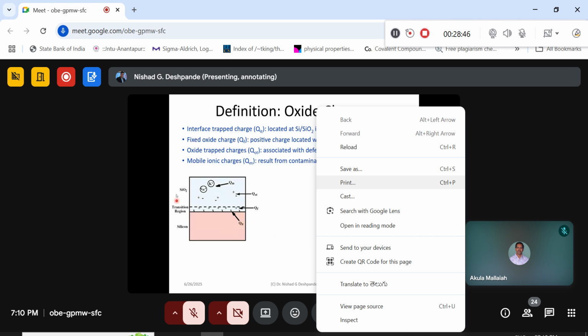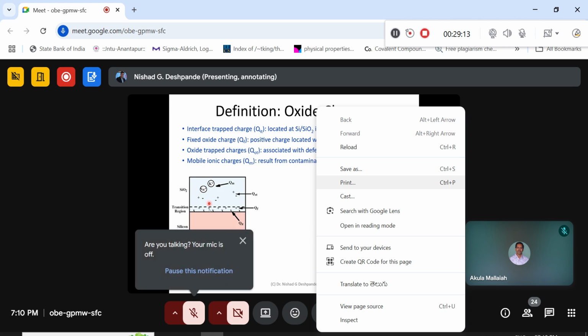Now what is happening there? We talked about this, right? We were also discussing it in our last lecture. You have a silicon surface. Let's say this silicon is crystalline, just for our assumption, and we are growing silicon oxide on it. So what we expect is that along the lattice, the silicon has to grow, so the whole region from the silicon to silicon dioxide has to be an epitaxial growth.